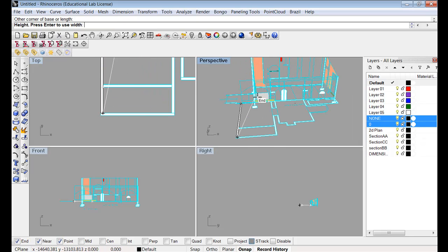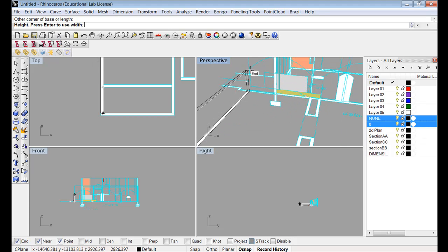And I'm going to do these walls individually because I said we can use this model again to laser cut out an actual model. If all of our parts are separate, I showed some of you the make 2D. I'll explain a bit more about that. We can take this 3D model, pick walls and so forth, and make it into a DXF again. Then we can put that DXF straight onto the laser cutter, and it would save you a lot of time. You don't have to sit there with a scalpel for hours.